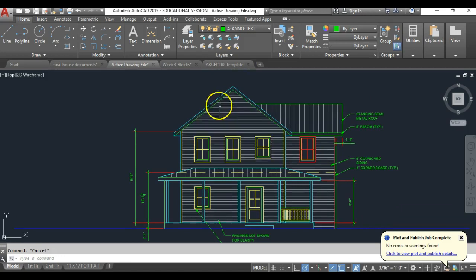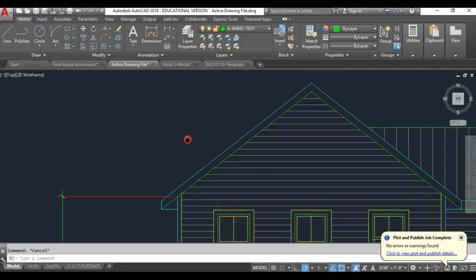And so what I'm going to do is I'm going to come over here and draw the slope line. And you have to draw this. There's no shortcut command for this. It literally is drawing lines and adding regular pieces of text. So I'm going to draw that triangle first. So I'm going to just sort of get close to the roof, you know, approximately there, just sort of eyeballing it, and draw straight up. And it's 9/12, so I got to go up 9 and I got to go over 12. And as long as you drew the roof correctly, your spacing is going to be the same.